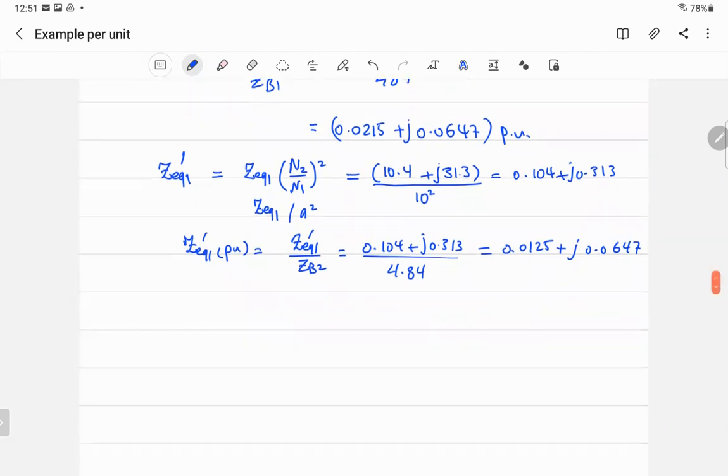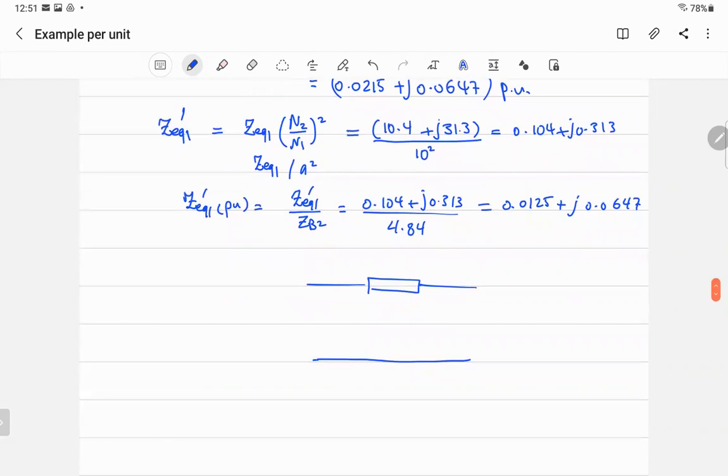So the equivalent circuit of the transformer is just an impedance like that, and it doesn't matter which side. That's V2 per unit, and that's V1 per unit. We don't write V2 dash now, because it doesn't matter which side you are on. You solve them per unit, and then if you want to find it on the primary side, multiply by the base of the primary.